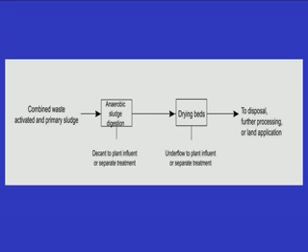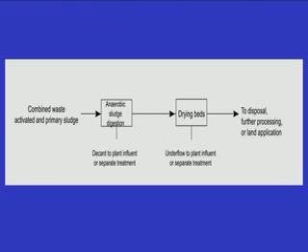So, within that time, whatever water is present in the sludge will be drying out, and because of the solar radiation, the remaining water will get evaporated and we will get a dried sludge which can be disposed of, or processed further, or we can use it for landfilling.